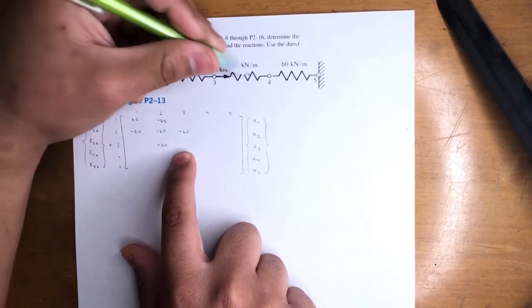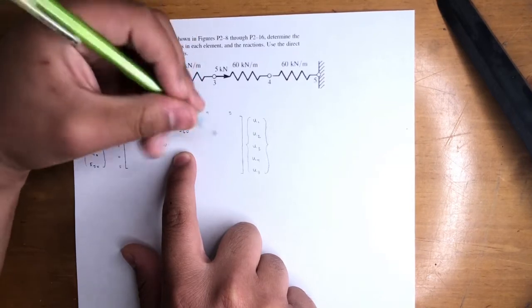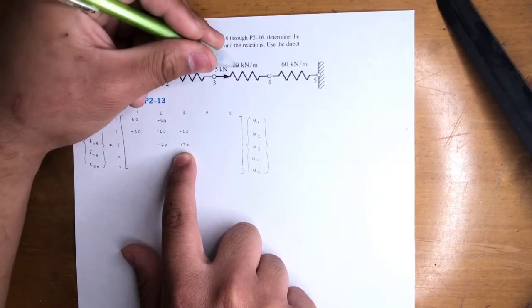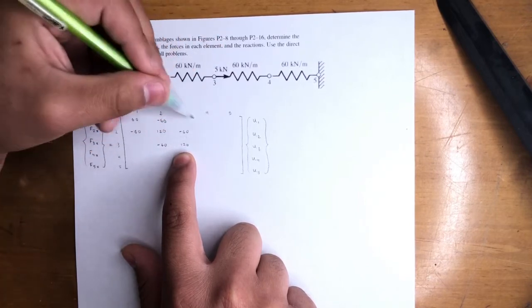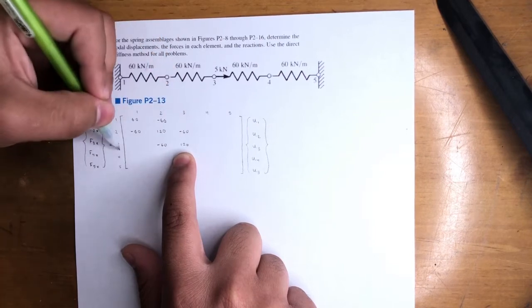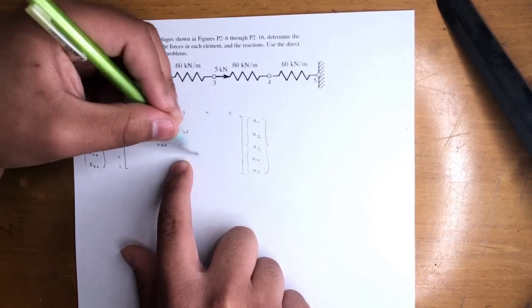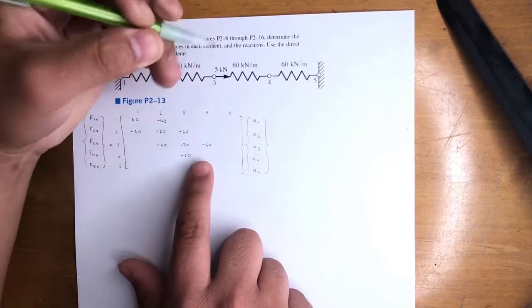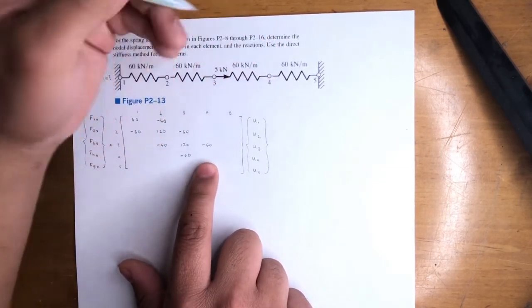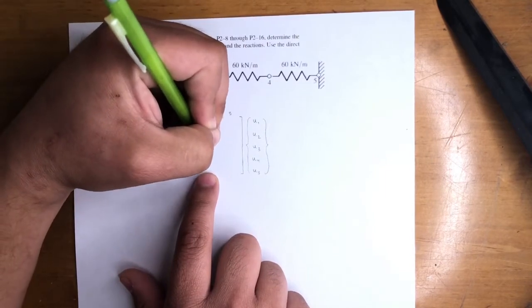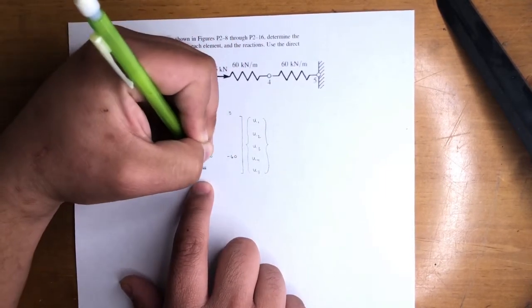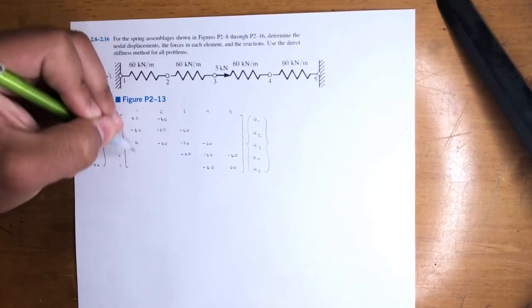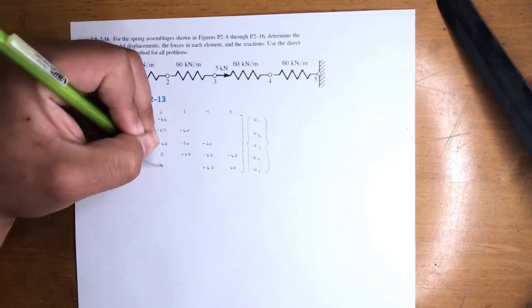Now it's between nodes 3 and 4 for the next one, so I won't have to erase again. It's going to be 120, because there was already a 60 from this one, and now we're adding this 60, so it becomes 120. So this one, this one, this one, this one, that means it's 1, 2, 3, 4. So this is negative 60, negative 60, and again one more time because 4 and 5, that's a 60. So this is going to be 120, negative 60, negative 60, and 60. All right, so we just fill in zeros where we didn't have anything.